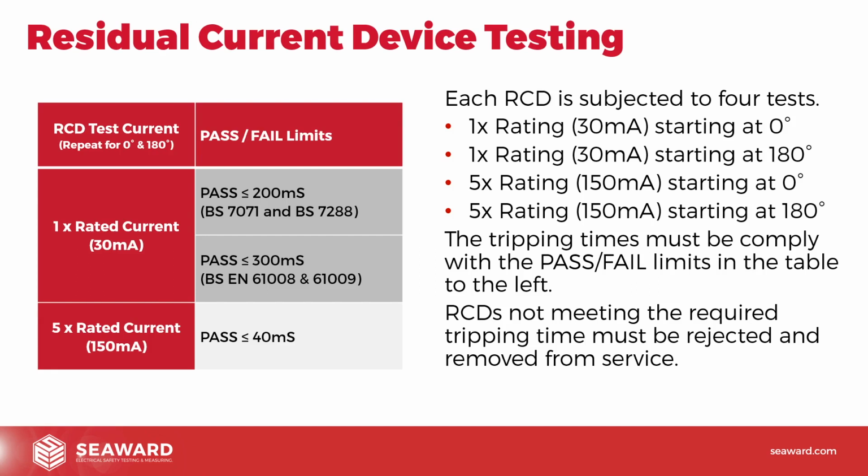Now, some older PAT testers you may find might only do a 1 times test. Some PAT testers don't even do that. But it is important now that if you are doing this, the Code of Practice, the 4th edition, does say that we should be carrying out these tests. And we should be measuring the tripping times. So it is important that we do have PAT testers that will actually carry out this type of testing.